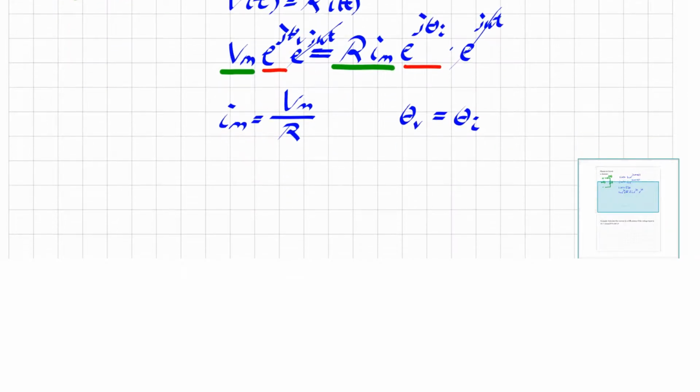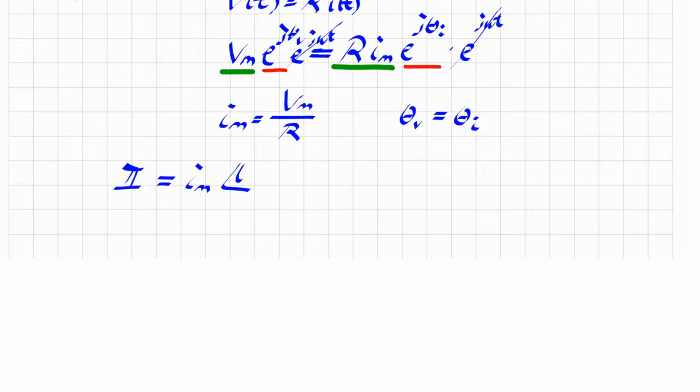And you can see then that the phasor, the current going through the resistor, has magnitude Vm over R, and the phase angle is theta v. So we find the current. And we can analyze the result and think about it. What is the characteristic of that relationship? We noticed they both have the same phase angle. So what do we call this? When theta I equals theta v, we call them in phase.